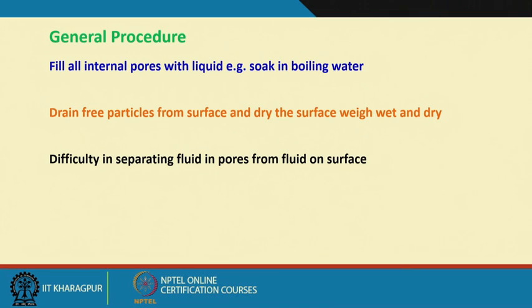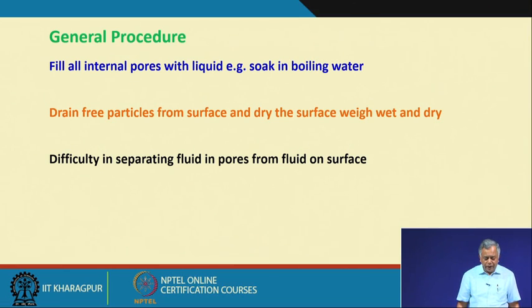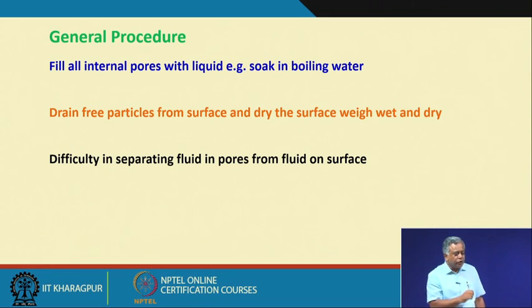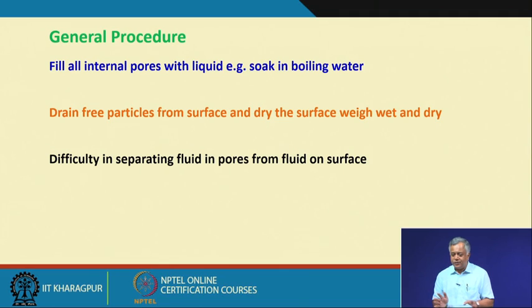So, the general procedure for filling all internal pores with liquid is to soak in boiling water. Initially you know the weight of the dry solid, and you soak it in boiling water to ensure that all your pores are filled up with water. Then you reweigh it after cleaning the surface of the particle to ensure there is hardly any water on the surface.